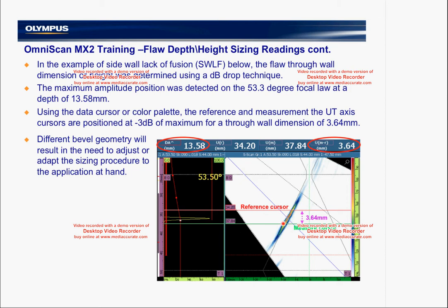So if the flaw appears at about 80% like this one does, and we can tell from the color palette here relative to this, typically new inspectors, junior inspection companies, or jobs where there hasn't been any or little upfront engineering for refining the sizing technique, people would generally oversize the flaws. So we want to be conservative. We can see here the 3 dB drop and the 6 dB drop position. Somewhere in between those, based on your weld bevel and your weld process, we will determine.